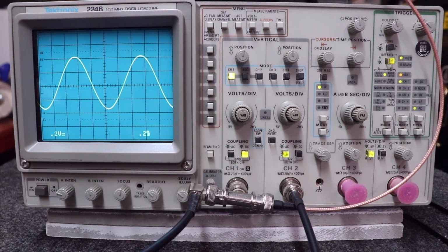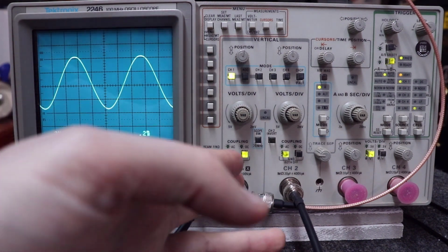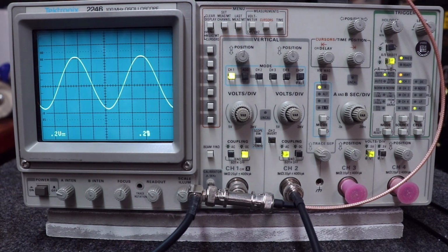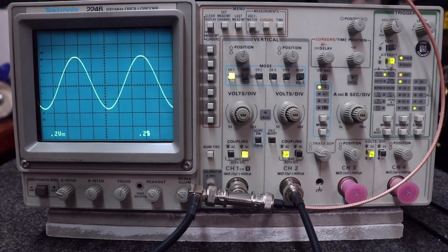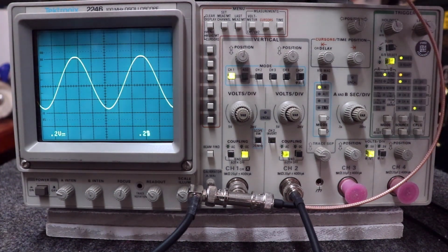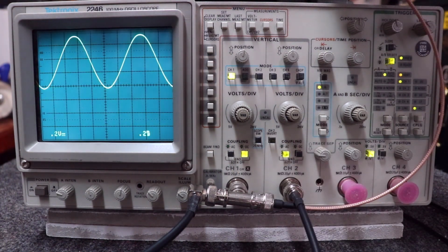What that is when you feed your signal into your oscilloscope right here, okay? It's an AC waveform feeding in, but sometimes your AC waveform is riding on top of DC. In other words, it's not biased around 0 volts. Maybe it's a 5 volt DC signal with a 1 volt peak-to-peak signal riding on top of it, which would mean it's going from 5 volts up to 6 volts, back down to 5 volts, down to 4 volts, and back up, okay? You can see that here, but if I happen to put this unit on DC, and let's just say I applied some